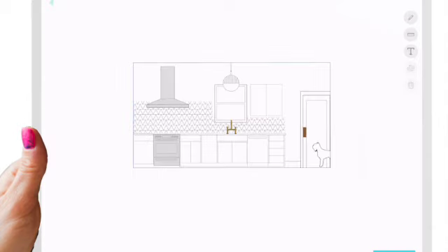The next step is to go to the dimension screen. On the dimension screen, you can use a pen and add notes or draw on the drawing. None of the objects are going to move, so you can add your details and everything is fixed. So you can see right here, I'm going to draw a line, add an arrow, and then I'm going to trigger the text function, add a note, type it in so it's nice and tidy, and then that item floats. So then you can drag it around the screen and place it wherever you would like.